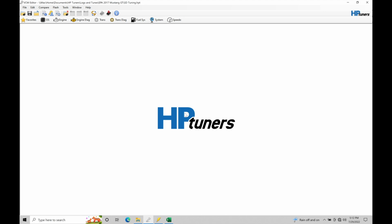So the first thing I want to do is jump into a calibration file and take a look at the speed density tables we have to work with, and talk about how this plays a role in our Mustang applications. If you are a truck application, speed density is handled a little differently because you have a MAP pressure sensor and you don't have a mass airflow sensor. The Mustangs have a mass airflow sensor, but we don't have a MAP pressure sensor. But in this situation, we have a hybrid mode to calculate what our air mass is going to be between MAF and speed density MAP-based formats. We'll talk about how this works in this video. So let's jump in here.